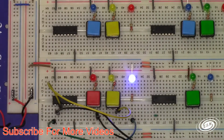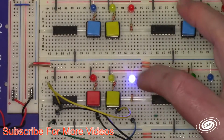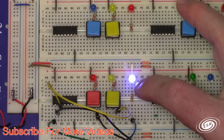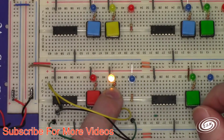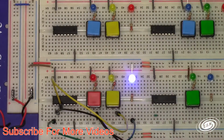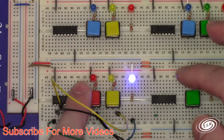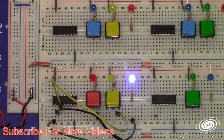There it goes. Something was tied low in the beginning. So there is the NOR gate. They're both 0, so the LED is on. If I press one, it goes off. I press the other, it goes off. I press them both, it goes off. So there is the standard NOR gate with one of these 74LS02.